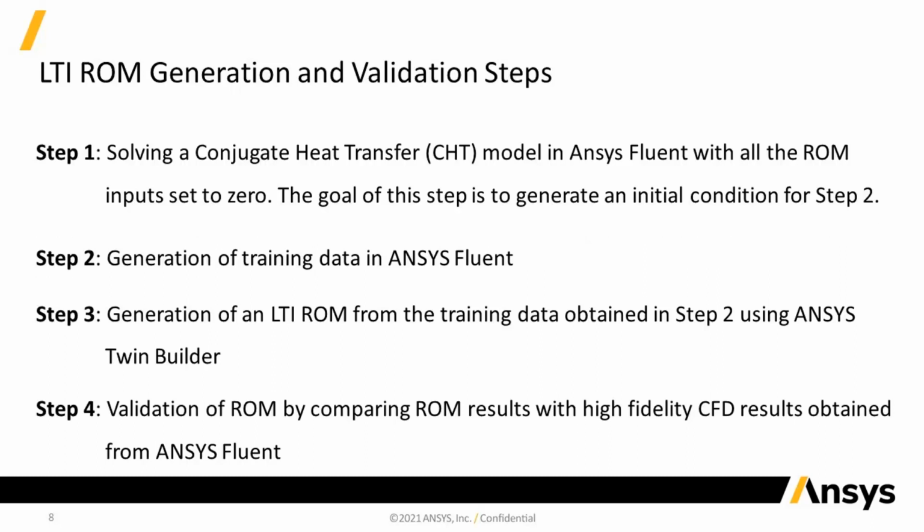LTI ROM generation and validation for a battery consists of 4 steps. In the first step, we solve a conjugate heat transfer model in Ansys Fluent with all the ROM inputs set to 0. The goal of this step is to generate an initial condition for step 2.